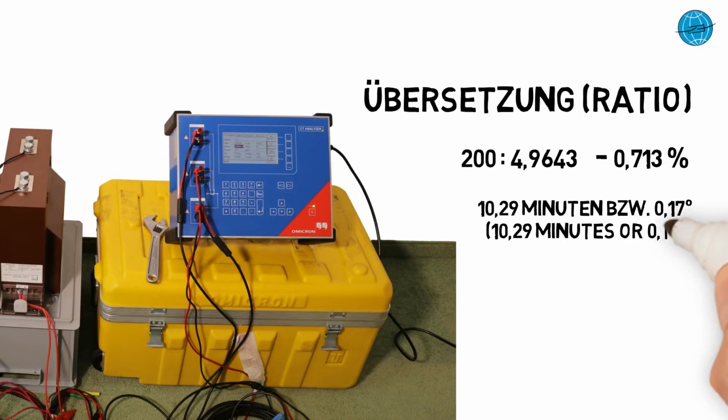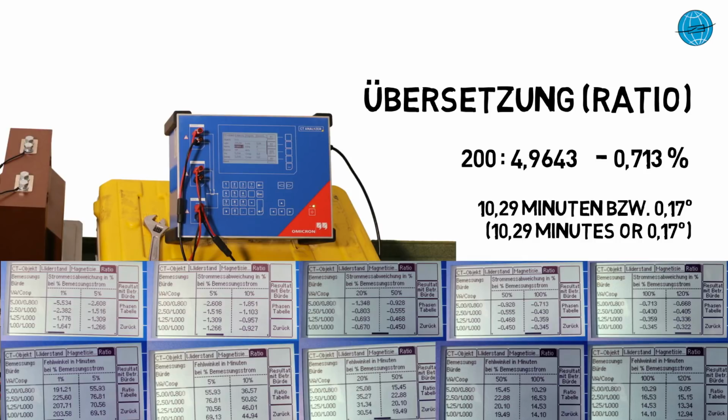Since a minute corresponds to the 60th part of a degree, this is approximately 0.17 degree. The CTA also gives very extensive results for the translation and phase angle deviation. Depending on the percentage rated current and with different design burdens, clear result tables are generated here.